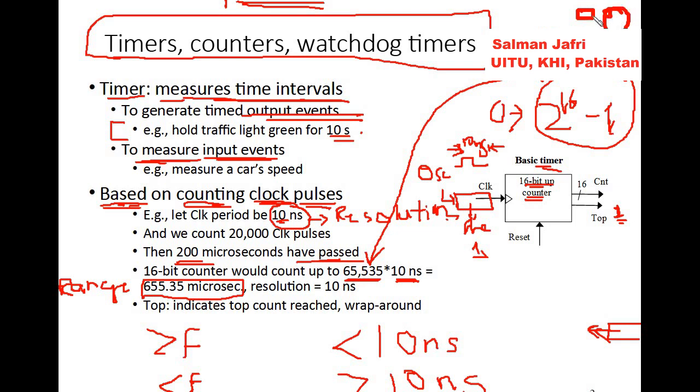When this reflecting surface is close to the laser gun, all the light that is shone on it is reflected onto the receiver, right? So we can find RPM using input events. This would be an input event. This would be high when this reflecting surface is near the reception end, and so on. So we can count the RPMs, and we can use the RPM to find the car speed.